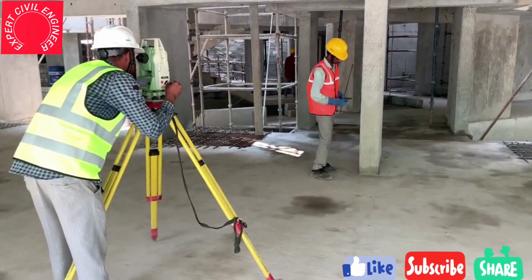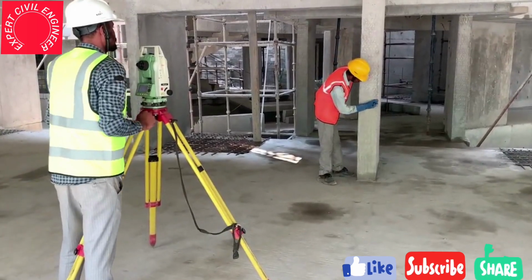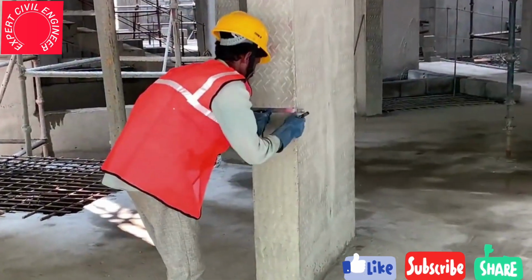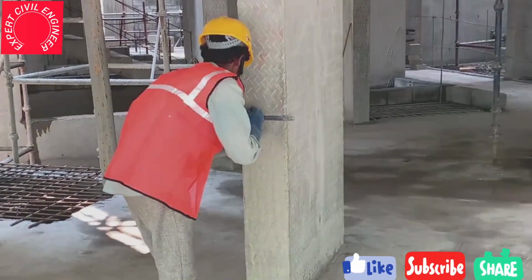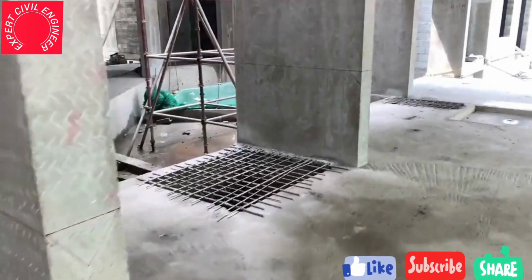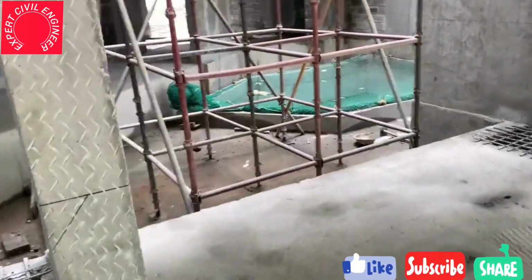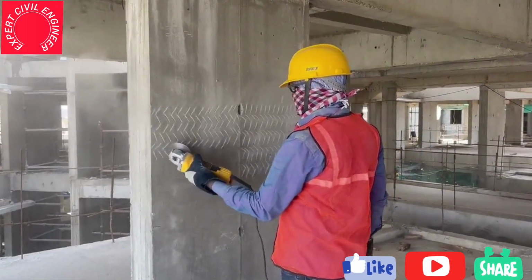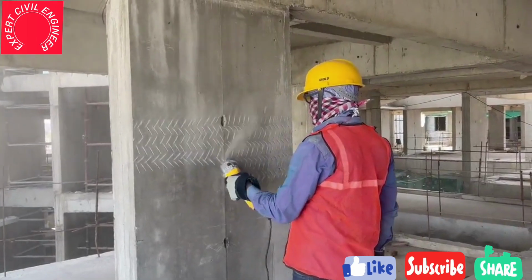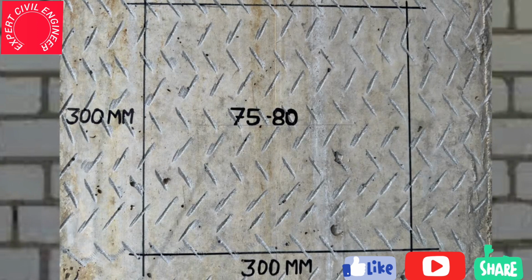As shown in the video, a reference level to be established at the work area. As a practice, a survey marking 1 meter finished floor level is marked on the column's shear walls as required. Kindly note, all concrete surfaces of beams and columns coming in contact with block work is to be hacked. There should be 80 indents per square feet and each indent should be 1 cm to 2 cm long.